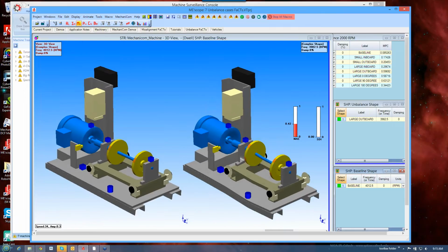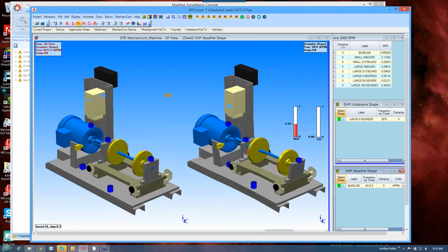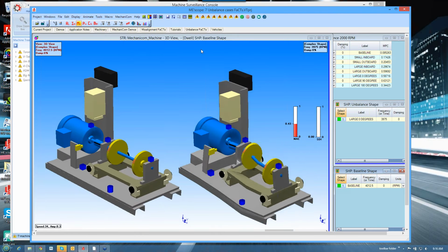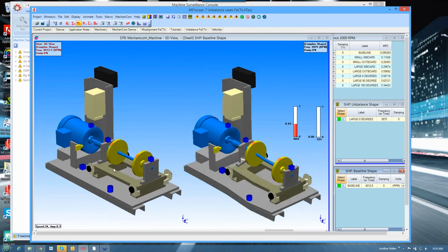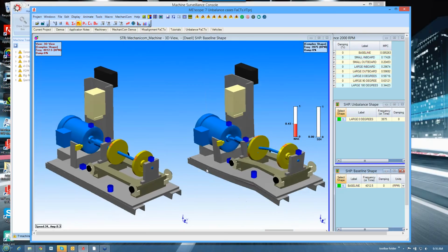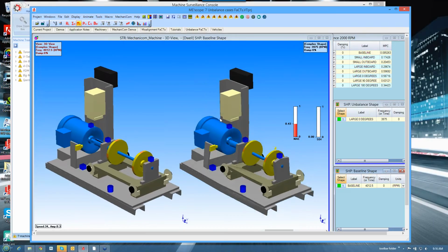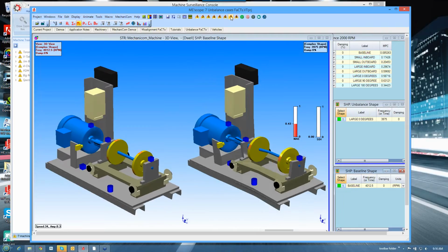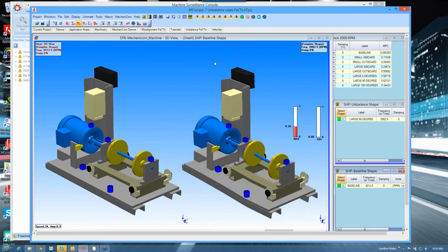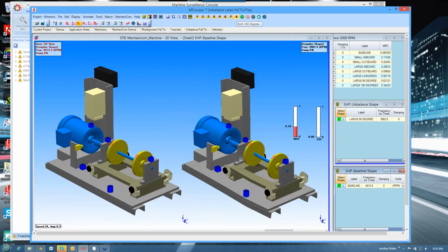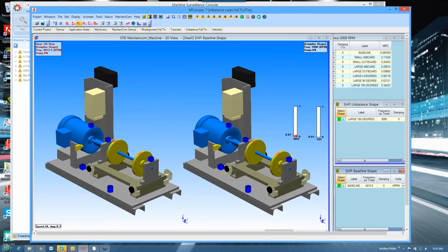Here's the worst case, and again, MAC is not indicating it as well. Now remember, on the left is the balance case of the second order, and then on the right is the unbalance where the two weights are 180 degrees apart. So what this is showing is certainly intuitive, that as we go up in these higher frequencies, they're even more sensitive to the unbalance, the second order.